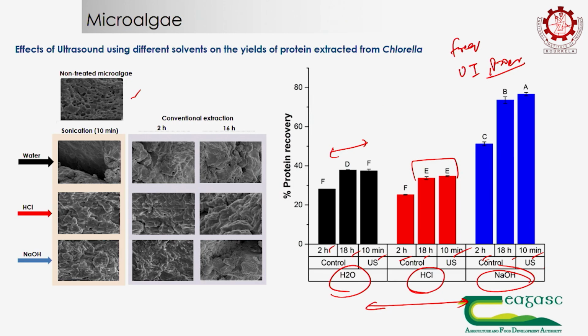That is completely wrong. If equipment is 1000 watt, you do not use 1000 watt. That is a power rating, that is the maximum power it will draw. If you use it at a lower intensity, it will be half of that. Say you have a heating radiator which says 3000 watt. That means in 1 hour it will use 3000 watt-hours, which means a huge amount of electricity.